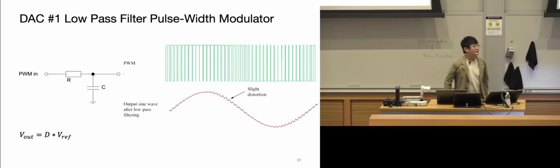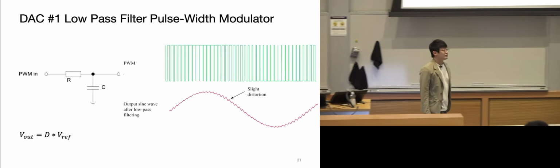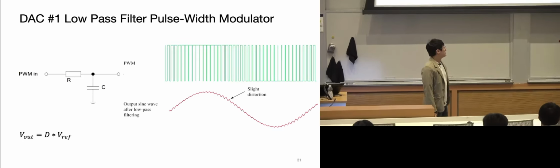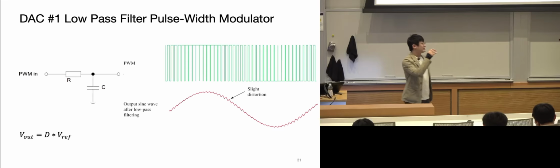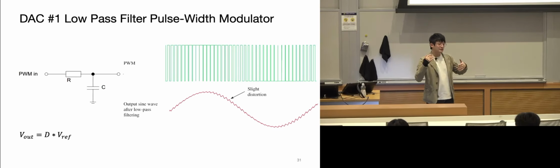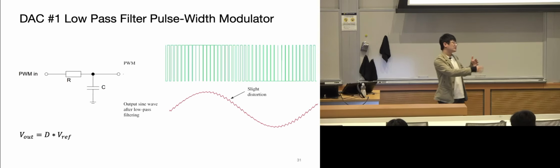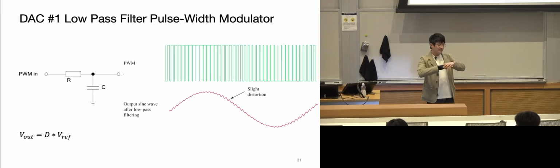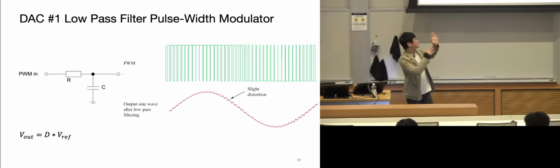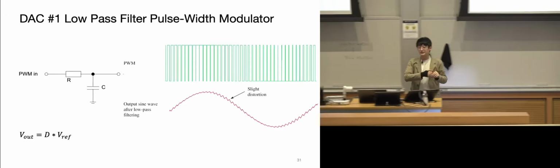Yeah. The point of the PWM circuit as a whole is just to use the DAC to create a sine wave in an analog form? Yes. So we're using the sine wave as a representation of what an analog signal would look like, because a sine wave is the simplest. It's just a one frequency signal. Obviously, in real life, it would be a lot of signals laid on top of each other. But the idea is the same. At each point you have a value that the DAC needs to produce, and this is how that value is produced at that time.